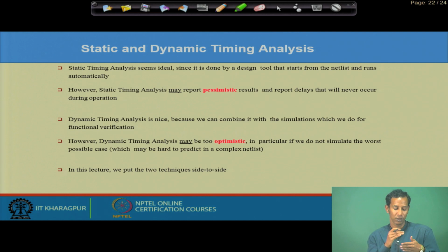If we consider the timing graph, depending on the inputs 0 or 1 on the interconnect path, the gate delays are the same, but the net delays differ depending on whether it is passing a 0 or a 1. What amount of delay is it actually considering? If I consider that, then it is dynamic timing analysis.